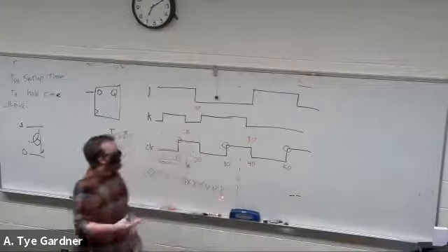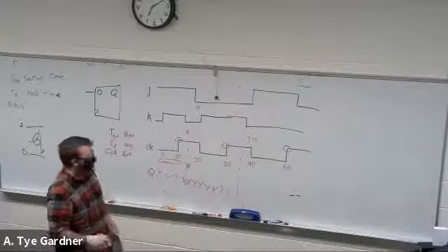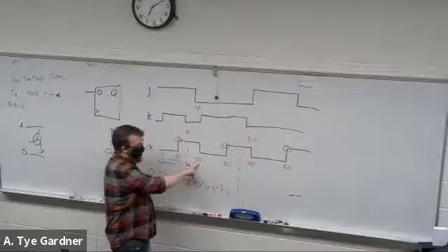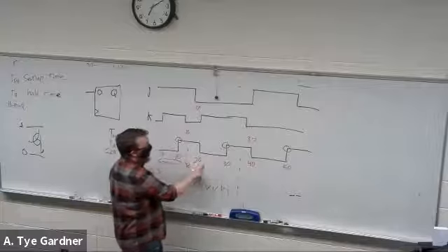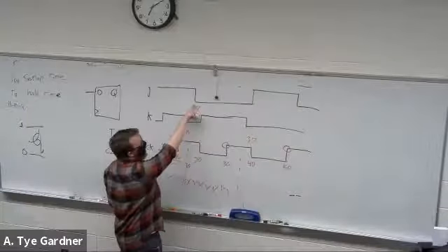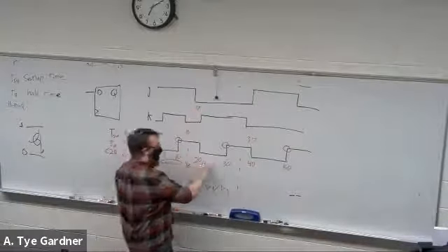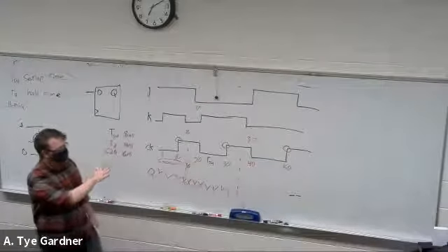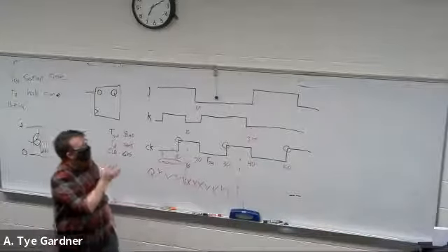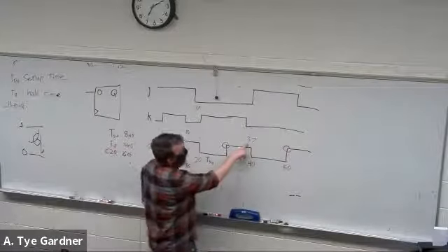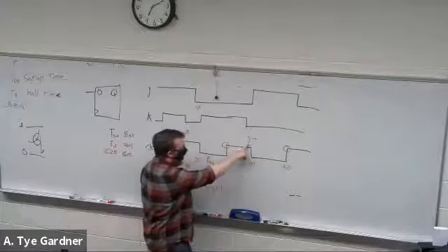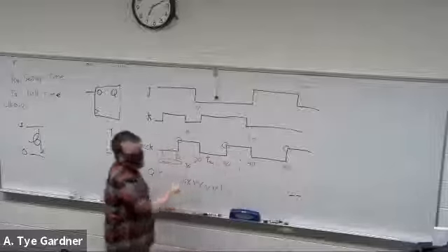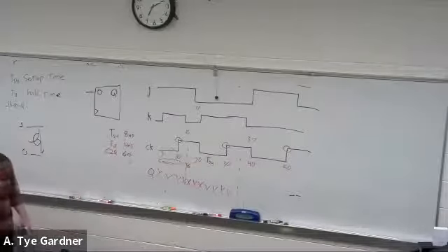Okay, well, are we okay here? Well, 20 nanoseconds earlier, 10 nanoseconds for this guy and even longer for that one. So here, T setup is great, right? We've got 10 nanoseconds, we only needed 8. T hold, well, I don't change until 37 nanoseconds, so I make it. So now I've clocked this in. What is the value? What is Q at 36 nanoseconds?